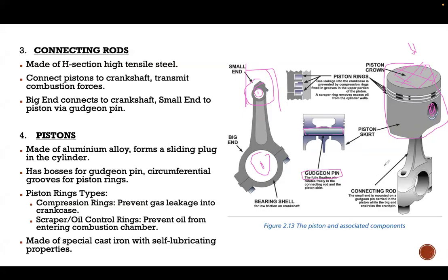Because in this place, let's imagine you have your crankcase. Your crankcase is going to be like this. And when your crankcase is in this way, your oil will start seeping through this piston crown, and it will leak through your connecting rods into your crankcase where you have oil in it, let's say if it is a wet sump system. So when you have oil mixing with the fuel, there are chances that this whole thing can burn and your engine will seize. So we should always be aware that these things can happen and you can have engine failures.